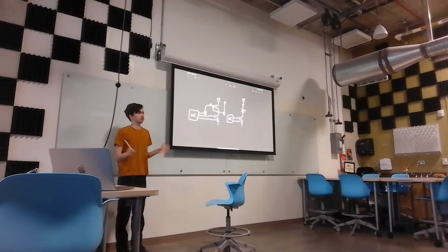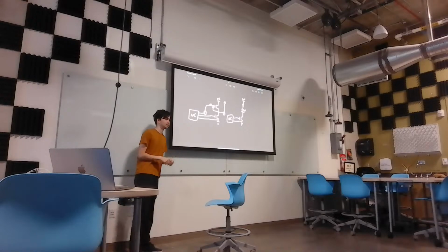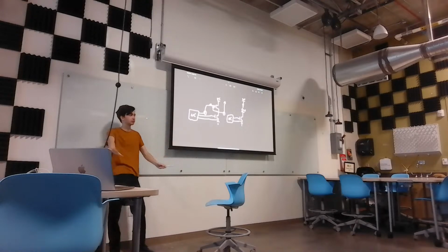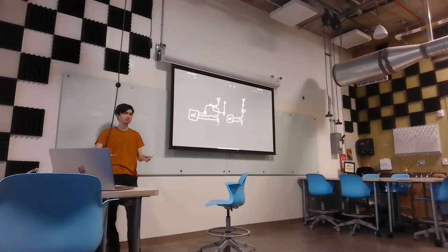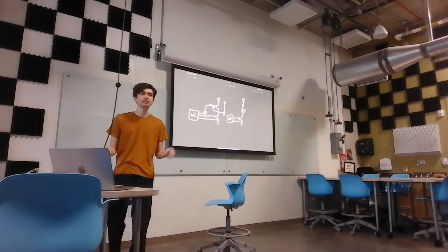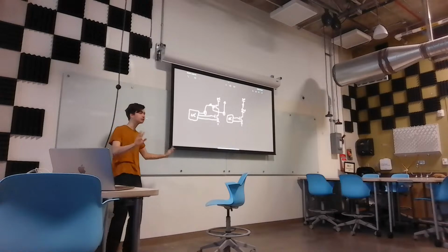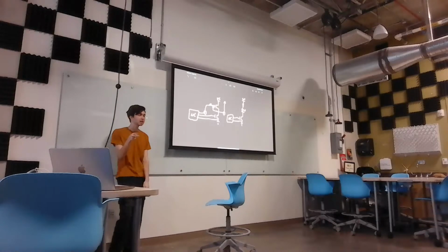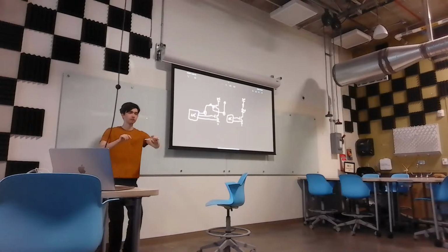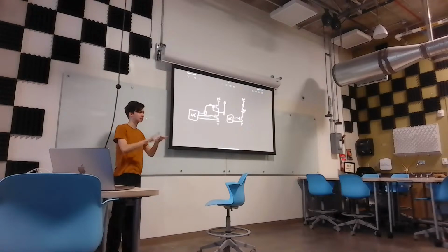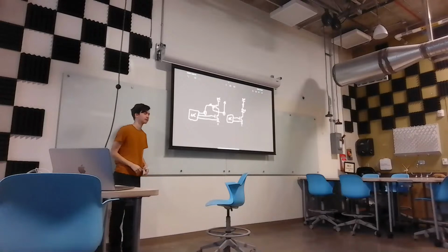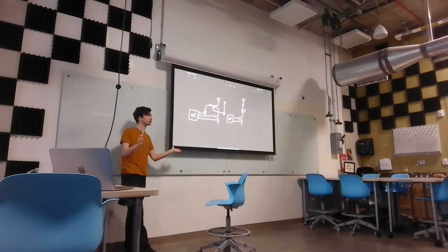This whole thing is a crazy circuit that is used all the time, because half bridges are super commonplace in power electronics. So you just get a chip. I got a chip called a half bridge gate driver. It has all the logic. You just give it 2 PWM signals. It'll convert them to 1 for the low side, 1 for the high side. It has the diode built in, because you need a diode, so it will instantly drain into your supply. And all you do is give it a capacitor. You say, here's that capacitor, you're good, and it works.